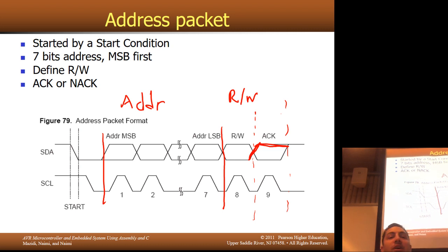That's right, attendance. So he kept saying Bueller because Bueller didn't respond with here, that acknowledge bit. That's the here in this case. It's the response from the student or the slave, basically the same thing, that says, hey, I am present on the bus. So if you send out an address packet and don't receive an acknowledge, this only applies to the address packet, chances are the chip's not there. You're talking to an empty classroom, okay? So there we go. That's an address packet.